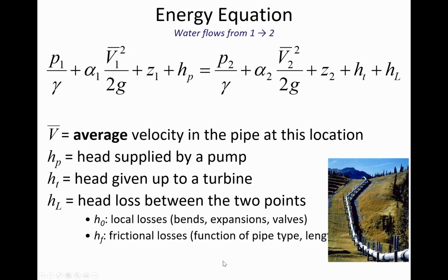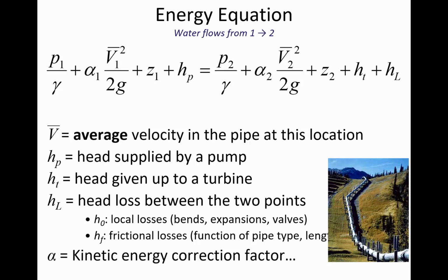And frictional losses are a function of the type of pipe that you're using, if it's rough pipe versus if it's smooth. And as you'd probably expect, a really smooth, let's say a glass pipe that has a very fine polished finish to it, is going to induce less frictional resistance than a rough concrete pipe would that has exposed sand. And so the rougher the pipe element, the greater the per unit friction losses are. Friction loss is also determined by the velocity of flow through the pipe at a particular time.